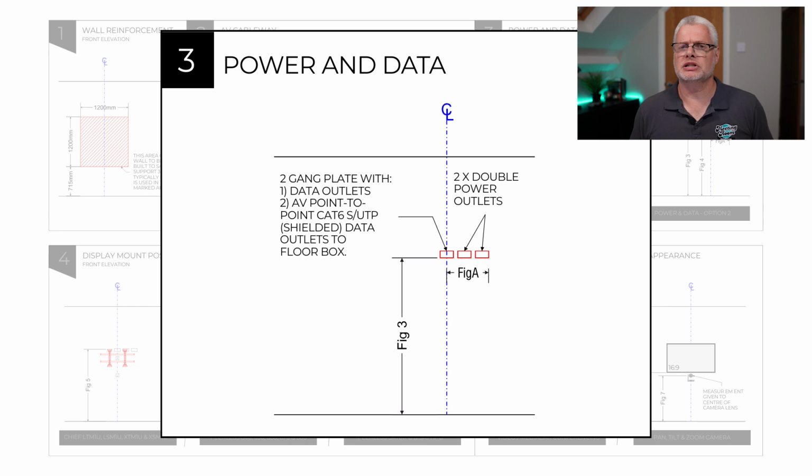For complex installations, I generally create a spreadsheet breaking down each room by device, showing what each of these items needs. So we would list mains power, network, point-to-point connections, specialist AV systems like HDMI and USB, any control system requirements, and then also fire alarm systems. Doing this in advance will also allow us to allocate Cat6 patch leads, HDMI fly leads, USB fly leads, and also any power adapters that are needed.